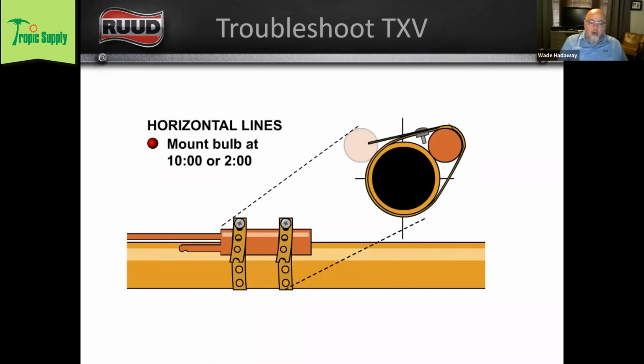It really depends on the design. We used to have coils that had expansion valves mounted inside the coil box. But if you do that, you're not necessarily getting the temperature of that line, you're also getting the temperature of the air inside the coil box itself. So I would just say follow OEM regulations.